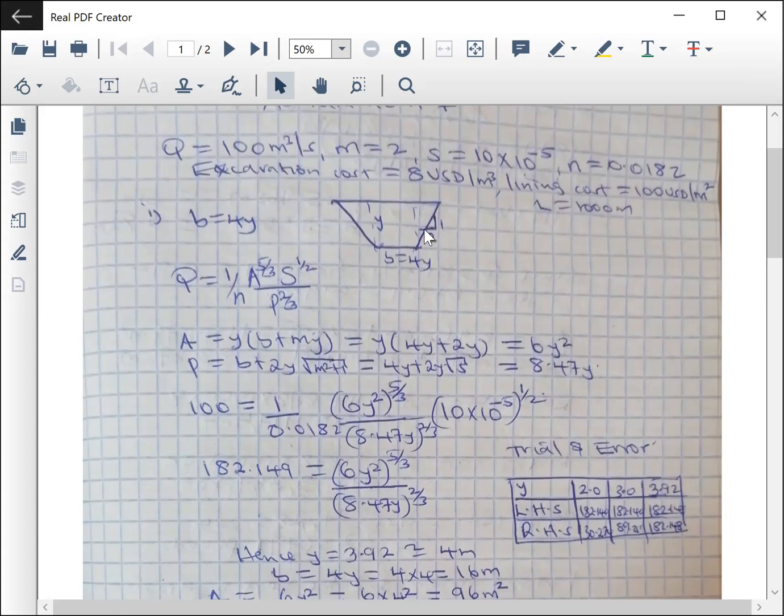Take it very keen, because we are saying the side slope 2:1. So 2 is horizontal, 1 is vertical. Another thing I want you to differentiate, remember, bed slope is S, but for side slope, we use M, whereby M will be equivalent to the first digit when the second digit is 1.